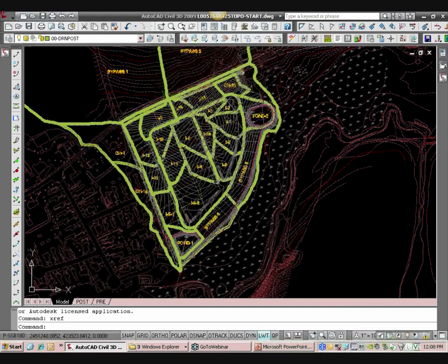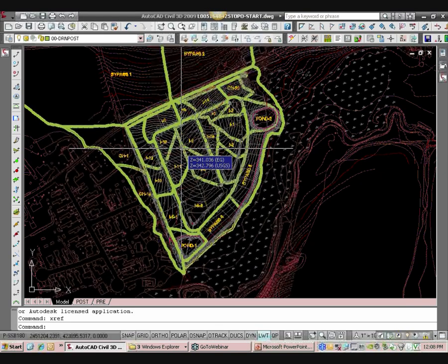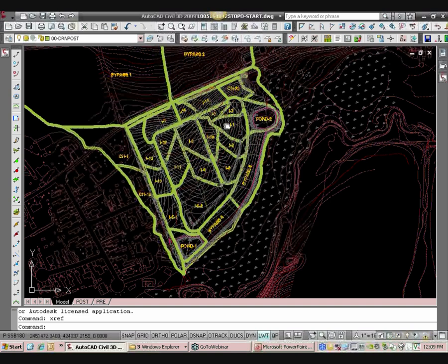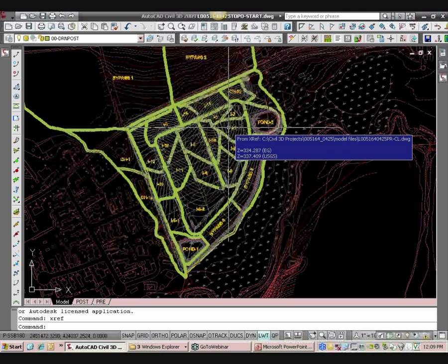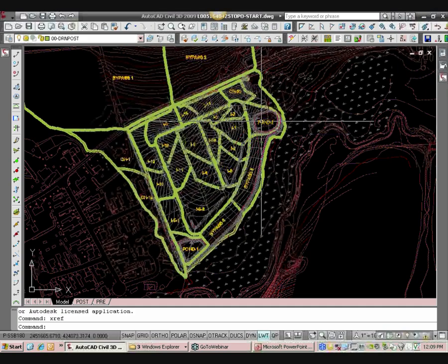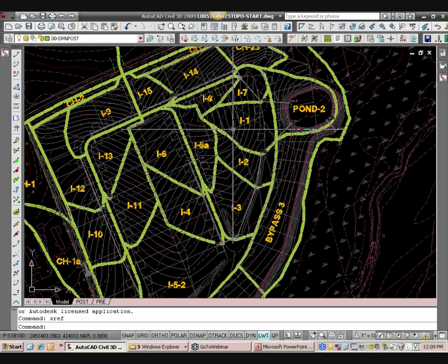Okay, so what is a topology? Well, we basically need three things to do our cover analysis, right? You need soil type, you need impervious coverage, and you need your drainage area. So there are three components of every drainage area: what type of soil, what the cover type is, and which drainage area it's in.